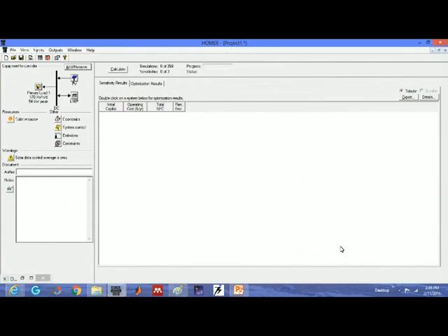No need of converter. PV is generating DC, battery is storing DC, load is DC. So directly PV to DC, battery to DC. Two-way connection communication is there with the battery, PV one way, load one way, right? But you see, I cannot model it to the grid. Grid I cannot feed DC, right? So I need a converter.